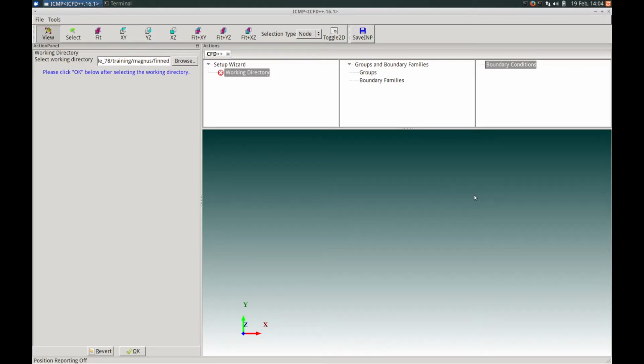In part 2 of our example, we will go over how to set up a simulation that demonstrates the Magnus force and moment calculations for a non-symmetric projectile. This example will be done in 2 steps. In the first step, we will run a steady state computation without any grid motion. In the second step, we will restart a transient computation from our steady solution, this time adding grid motion.